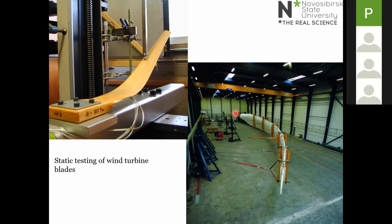So a wind turbine blade is a complex cantilevered composite shell structure, and it has very anisotropic properties, because when a wind turbine blade is made, most of the fiberglass reinforcement goes to give you strength in the radial direction so that you withstand the bending of the blade due to the pressures of the wind.